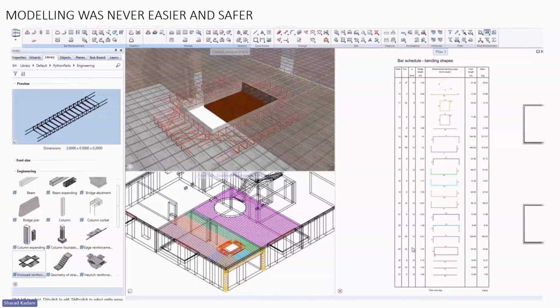One good feature is that there could be some openings for which we don't need to cut rebar. So we select the openings wherein we need to cut the rebar, and we can skip the openings wherein we need the bars to pass through it. That will be done at the side. All these facilities and features are available in Allplan.